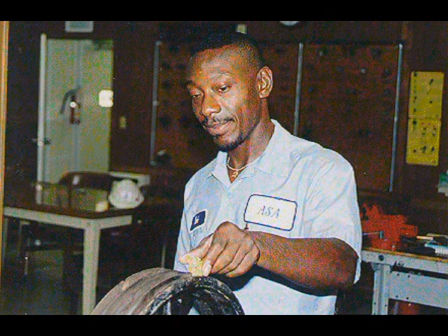Sheaves should be kept clean. Dust and rust can cause worn sheaves, which in turn can damage the belts. The belts themselves should be kept clean. Dirt, grit, oil, and acids can ruin belts.